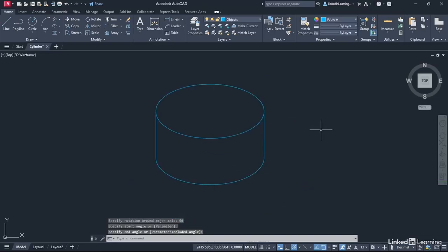If you zoom out slightly, there is an isometric representation of a cylindrical disc using your ellipses and your rotation. Very quick and easy, but it gives you a good idea of what ellipses are there for and what they're useful for. They can be used for other geometric shapes like flowcharts. You might even have an ellipsoidal shaped dining table on a floor plan, for example. So you can see that those ellipses are very useful as an extra drafting tool in your AutoCAD skill set.